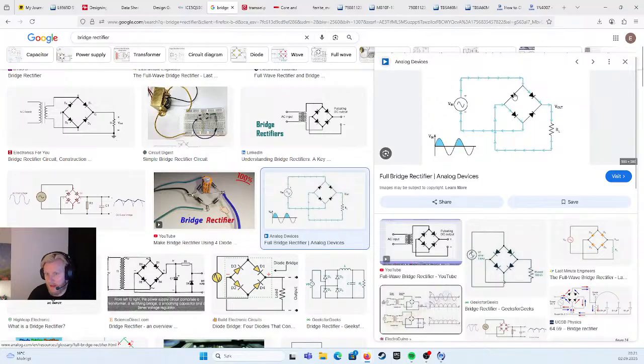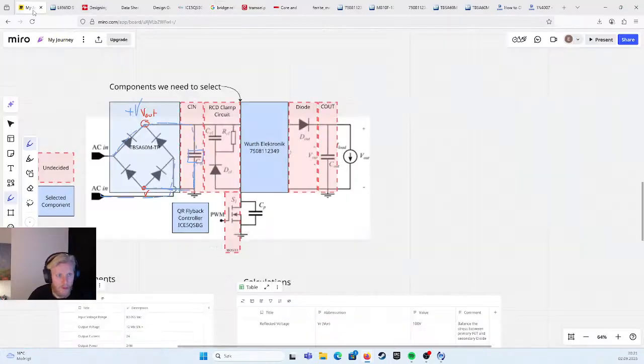And this is reverse biased. This is forward biased. So it will conduct this way and out in the V out and across the load and back the other way, back into the source again. So in this case, that would be down here, this way, and then back into the source.